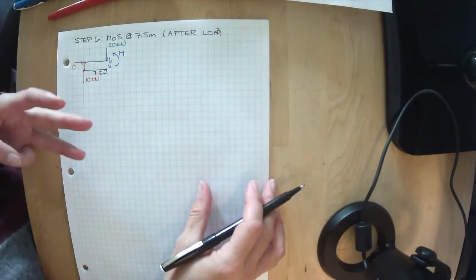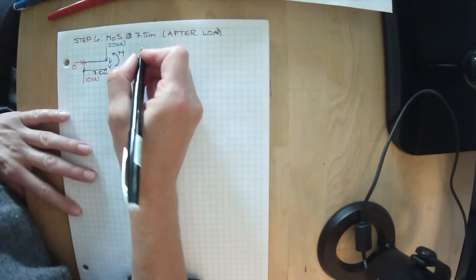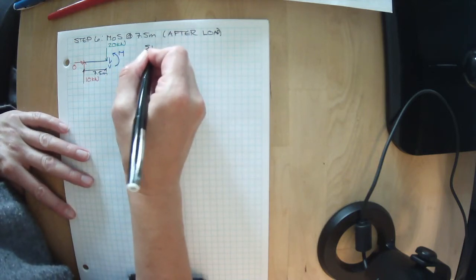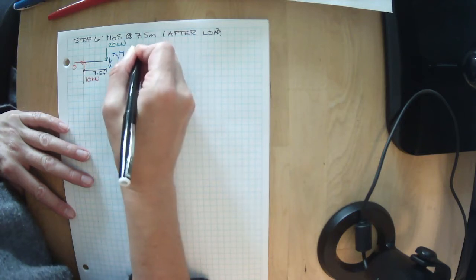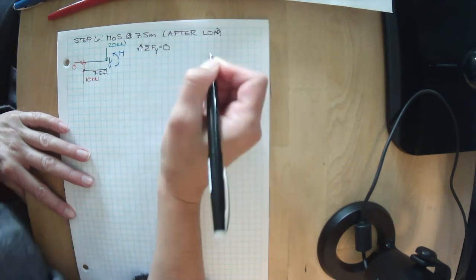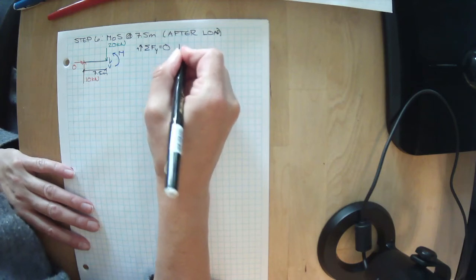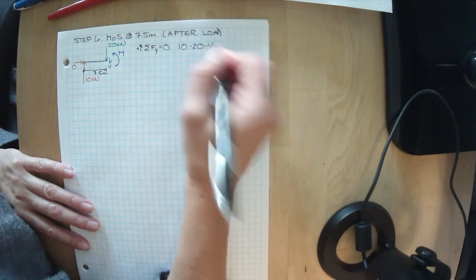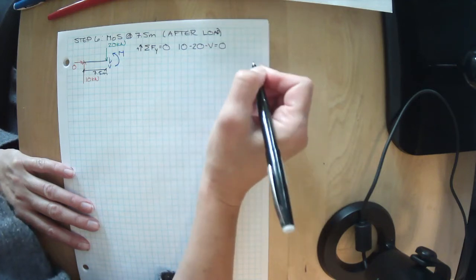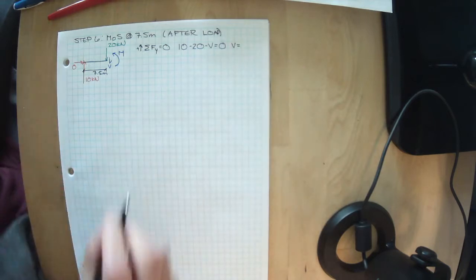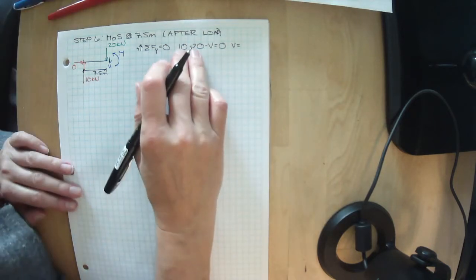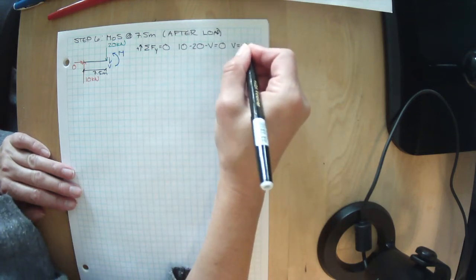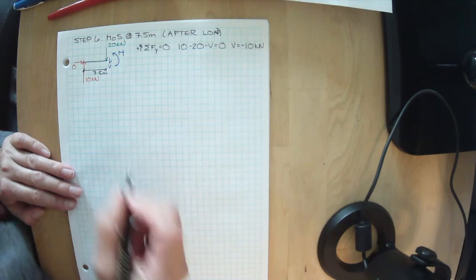Okay, we've got 3 equations. Let's go for it. You can see that we don't often need all 3 of them when we're doing these. Sum the forces in the y direction, where everything upwards is positive. We've got 10 kilonewtons upwards, 20 kilonewtons downwards, and our unknown shear acting downwards. We can rearrange this. We bring our V over here, 10 minus 20. We have minus 10 kilonewtons.